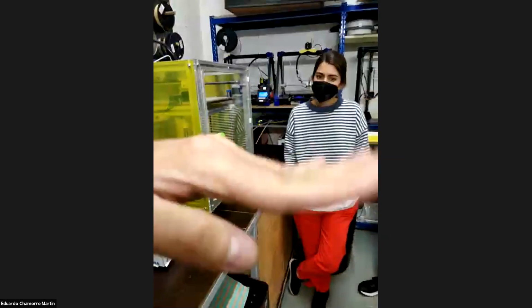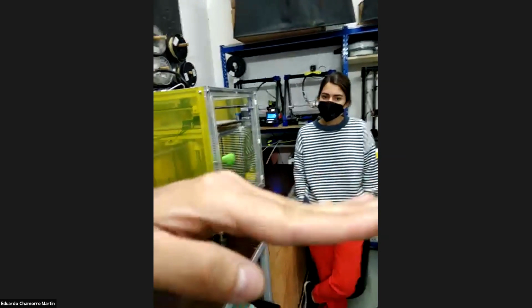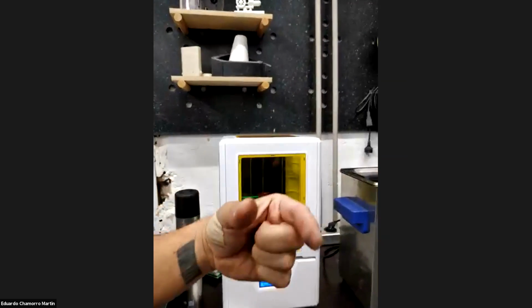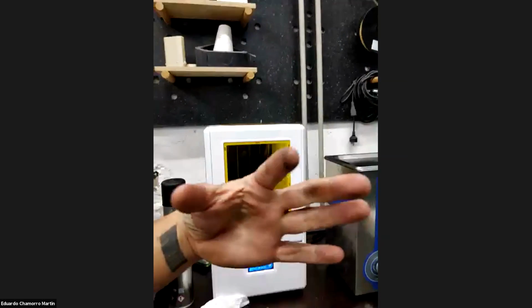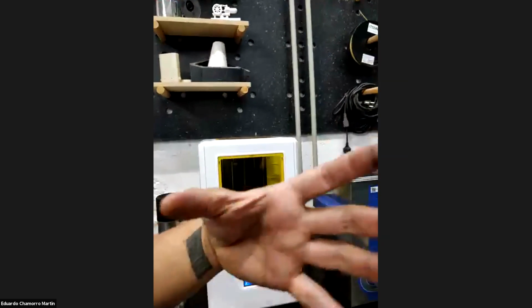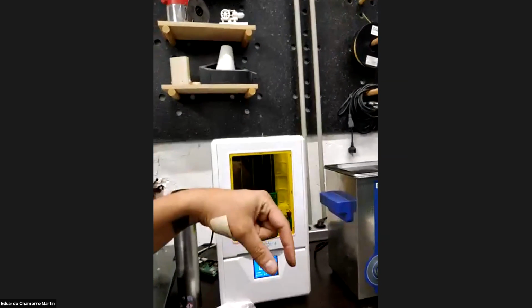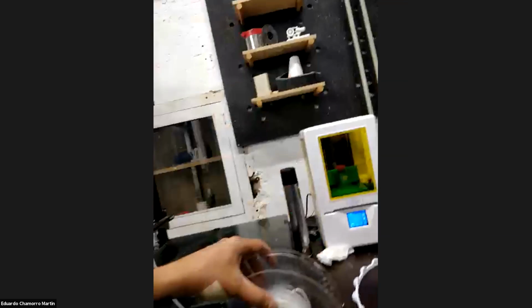We have double ones, really huge, to have a lot of stability on the Z. For the movement, this one uses a threaded rod. You have two really big bearings, so you can go with a threaded rod and not a ball screw because you already have a really sturdy system on the other side. But ideally, you should also go with a ball screw system in the Z, because as you only have one thing determining your whole quality, you want to make it good.